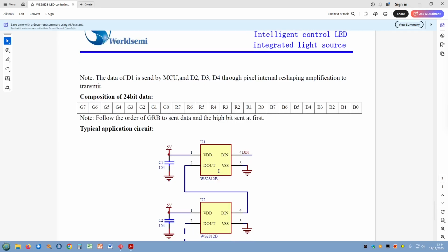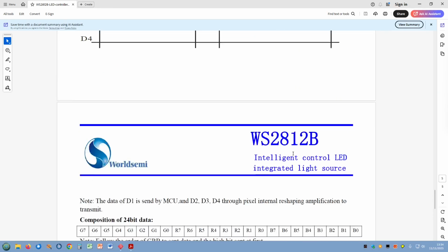So I'm going to do 9 of these. So that's 9 LEDs with 3 bytes on each. That's 27 bytes in all. And we'll actually reserve 27 bytes of memory in a microcontroller, and we'll build up what the display should look like before we transmit it. And then I'll do one loop inside the other. The first loop will go through the bits, and the outside loop will be stepping between the bytes. We just have to put them in the right order.